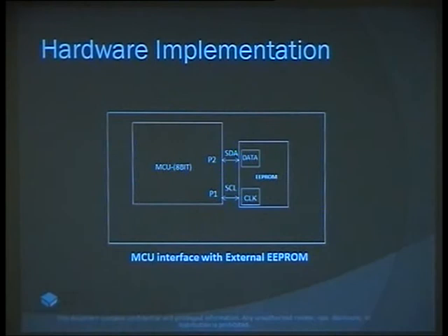You have PWM peripherals, right? So you have PWM peripherals, you have PWM registers. So yes, you can activate it from the application layer, but you already have PWM modules, timing registers, right? Those can be activated by using files in the peripheral layer as well as the API layer.